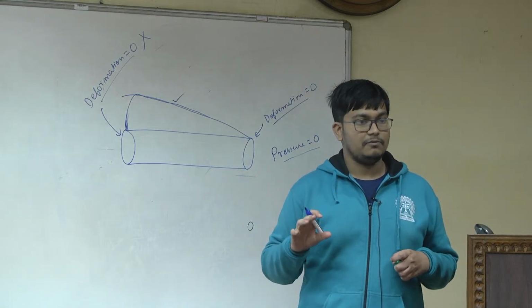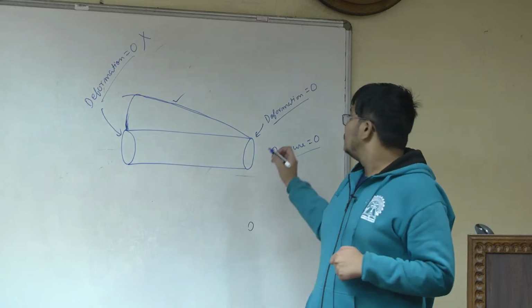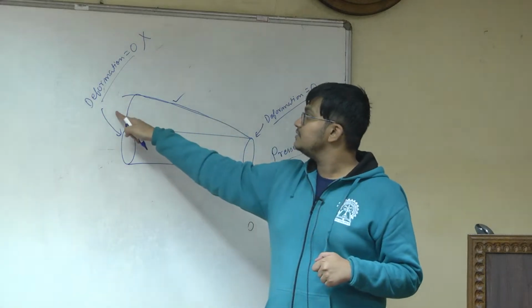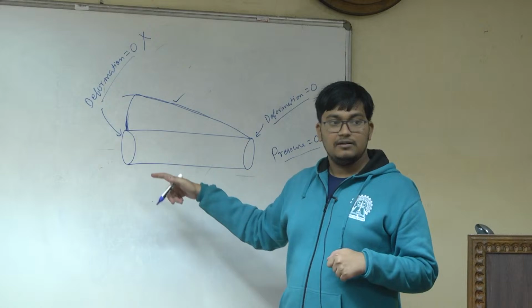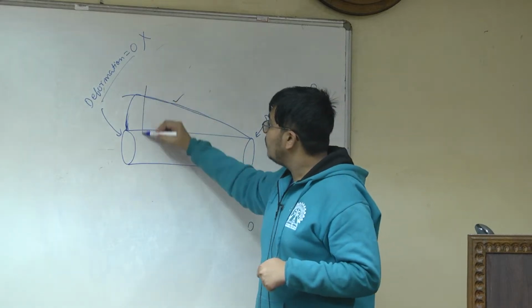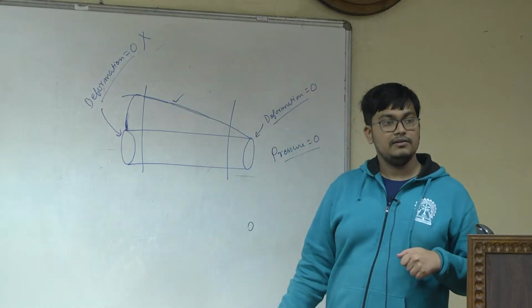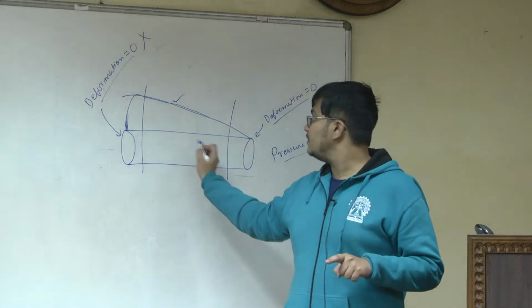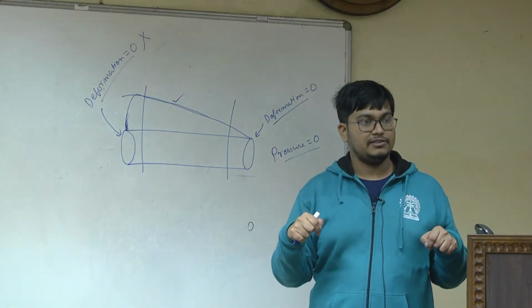That value we will not be able to get using the MRI data, phase contrast MRI data. So for both the cases we will have to forcefully impose this 0 deformation boundary condition. So near the inlet and near the outlet, the results which we will be getting will not be correct. In between, the results will be correct, because we are forcefully imposing that boundary condition.